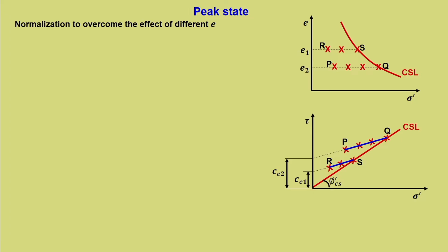We are basically discussing in depth the understanding of peak and the cohesion behavior of the soil. Definitely if there is cementation, it is bound to exhibit cohesion, and for that reason we can always extrapolate the results, so that the intercept can be considered as cohesion. We have seen that different e1 and e2 will result in different c dash and phi dash characteristics for the peak line.